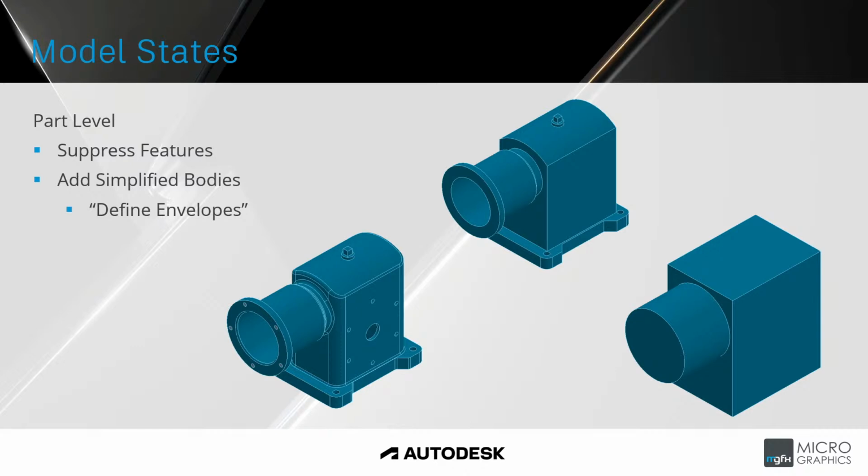So 2 extrusions, one for a box, one for a cylinder, which define our envelopes. This was manually done in this example, but later on we will also see how we can automatically define envelopes. So model states at part level allows you to suppress features and turn off detail within the design.